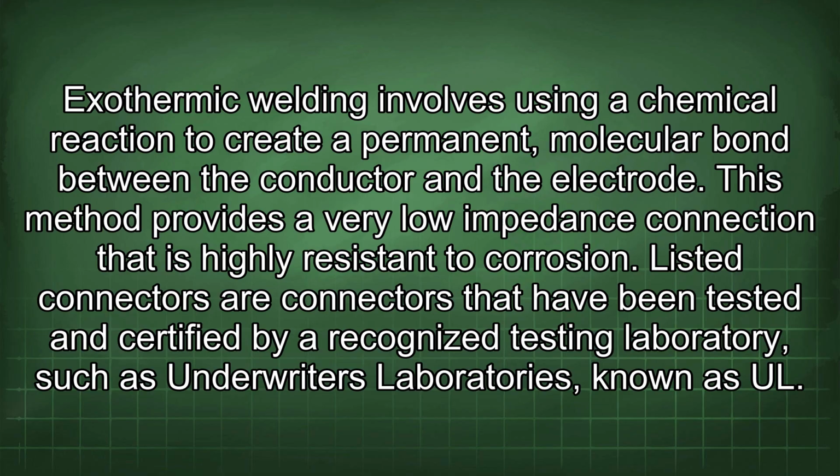Exothermic welding involves using a chemical reaction to create a permanent molecular bond between the conductor and the electrode. This method provides a very low impedance connection that is highly resistant to corrosion. Listed connectors are connectors that have been tested and certified by a recognized testing laboratory, such as Underwriters Laboratories, known as UL.